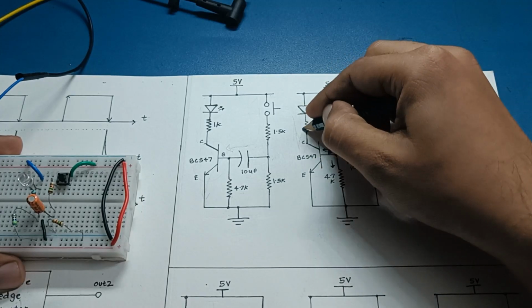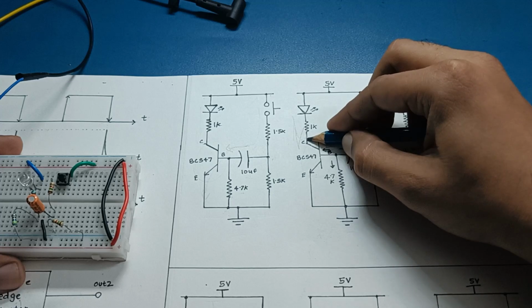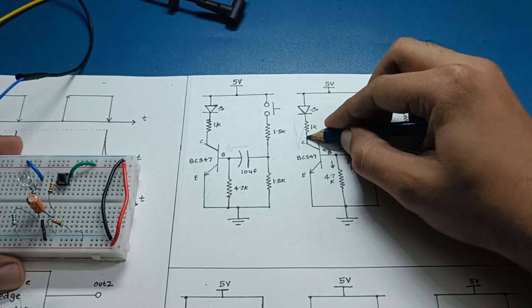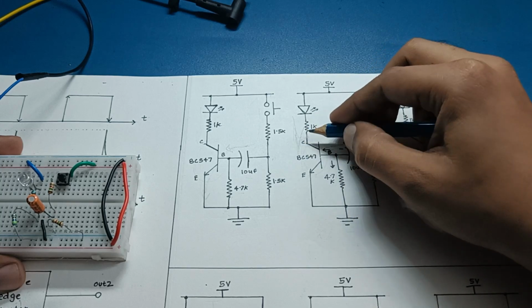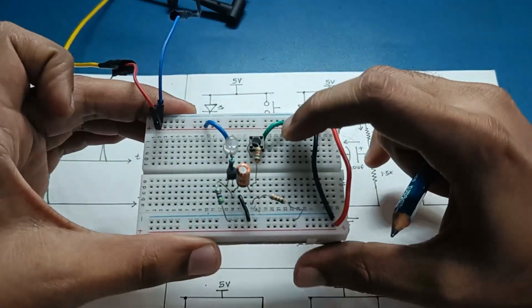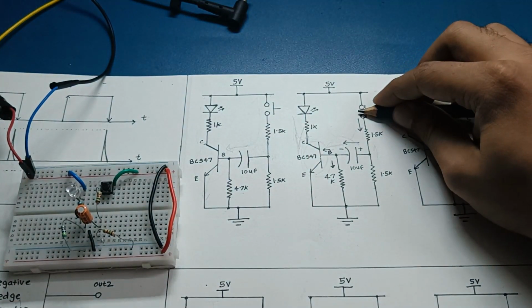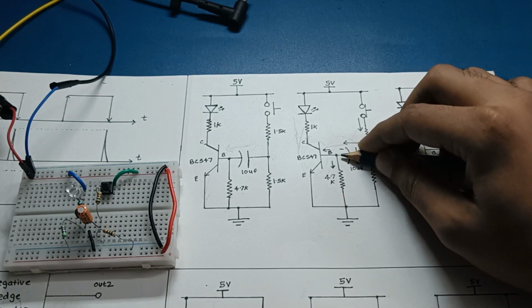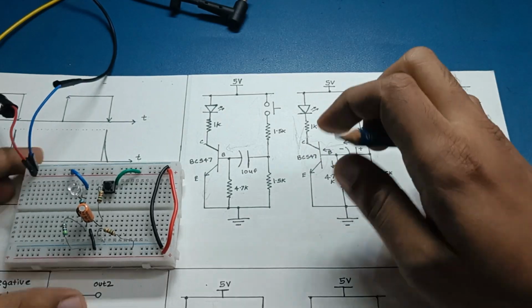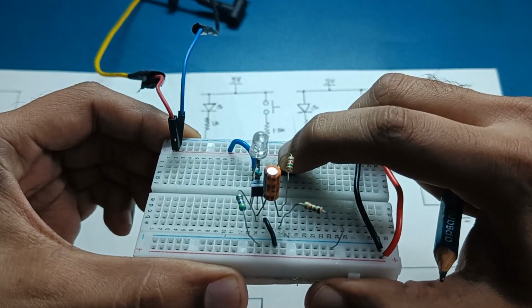This is a negative voltage spike as this transistor is NPN, it switches ground. Normally it's 5 volts here, but when it turns on, there will be a voltage drop. So you will get a negative voltage spike here. I will press the switch, and while the switch is still pressed, the capacitor is fully charged, but the current is 0 now. That's why the transistor is off. So I can keep the switch pressed and the LED is still off.